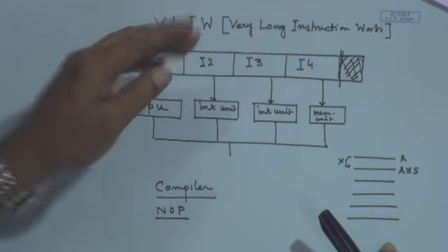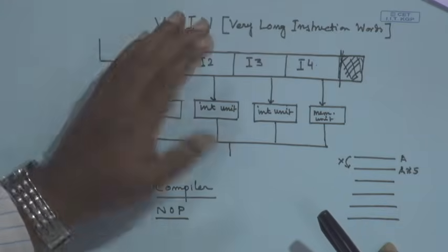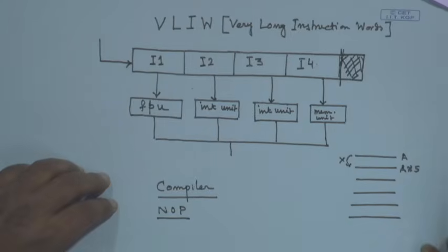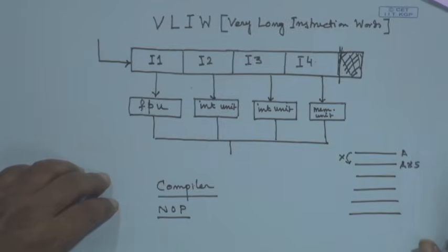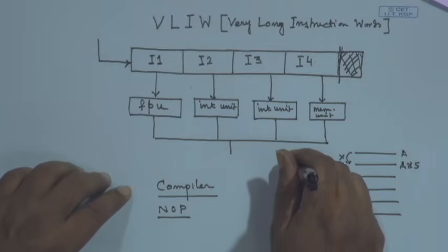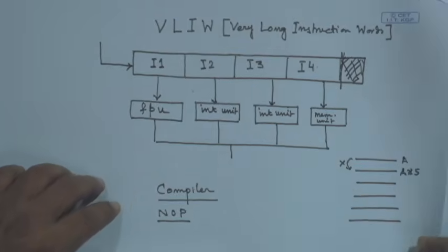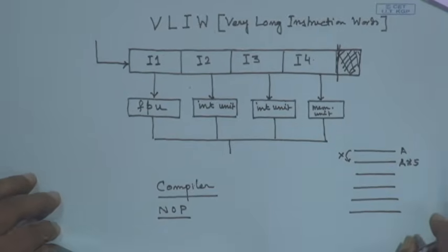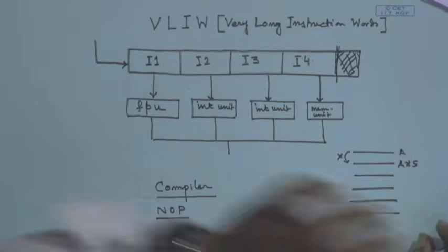Therefore, often a lot of space is wasted and we get low code efficiency, when I want to reduce the size of the code. That does not always happen to that extent, but to some extent it certainly pays off, and this is another architectural move to reduce the power. Are these slots prefixed to the floating point unit? By the instruction set, yes. The instruction set has a certain structure, and we have to fit the instructions there.